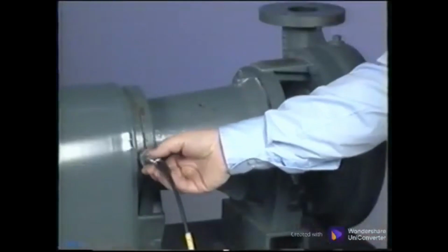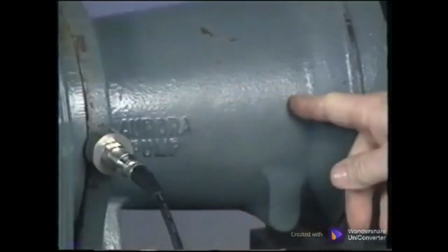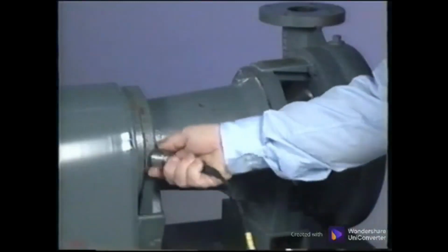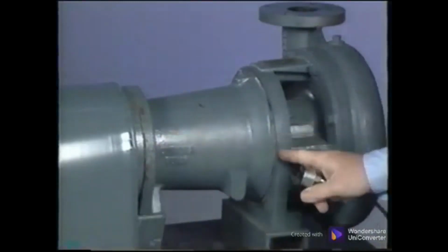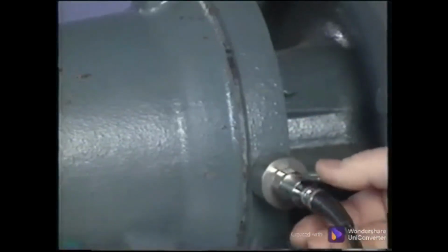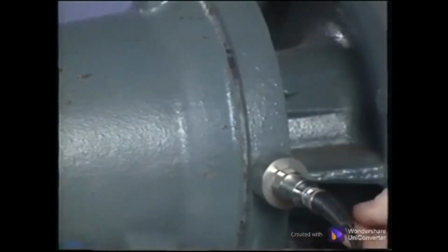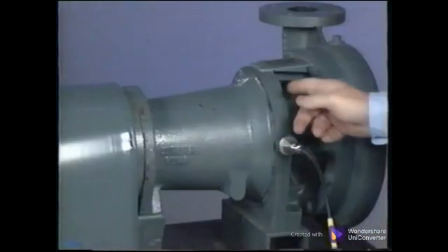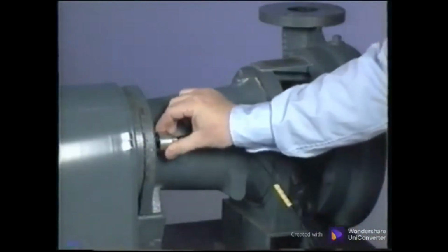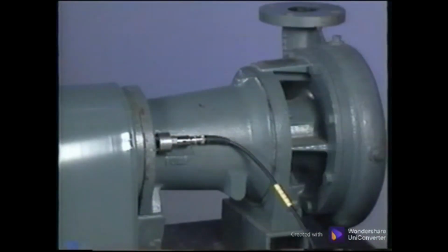The center section of these pumps is hollow, and measurements should not be made here, as the signals will not be accurate. The outboard bearing is located in this area, and the horizontal readings should be made here. Axial measurements could be made at either end of the pump, but the impeller end tends to show energy due to flow, which can mask other problems.